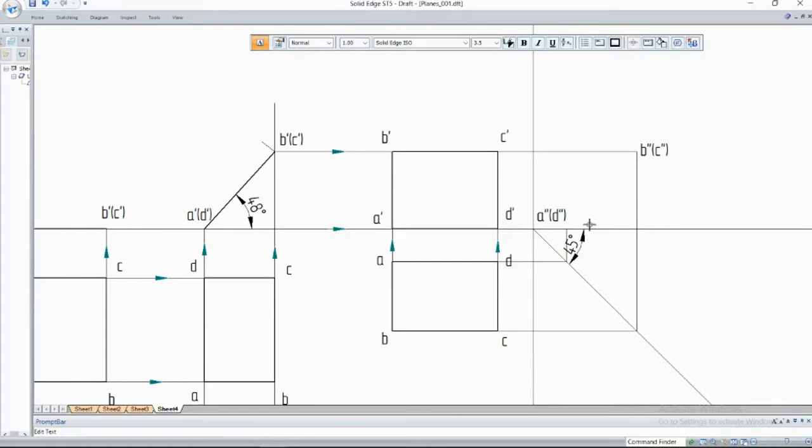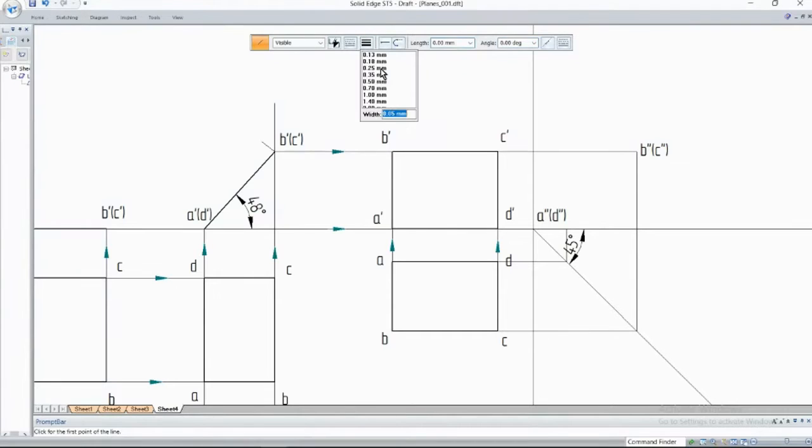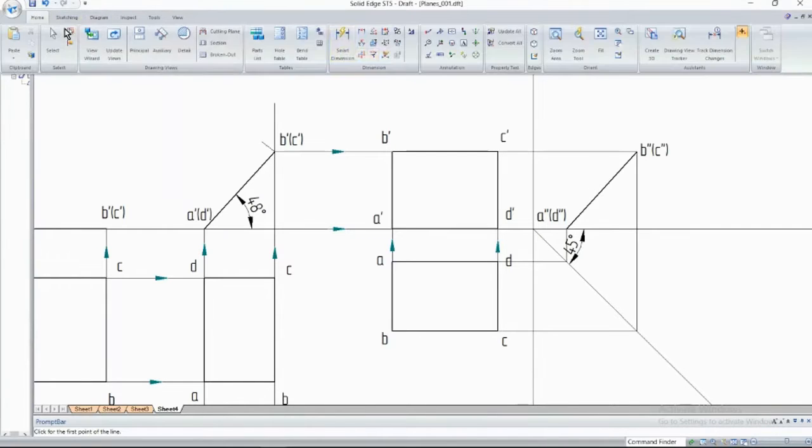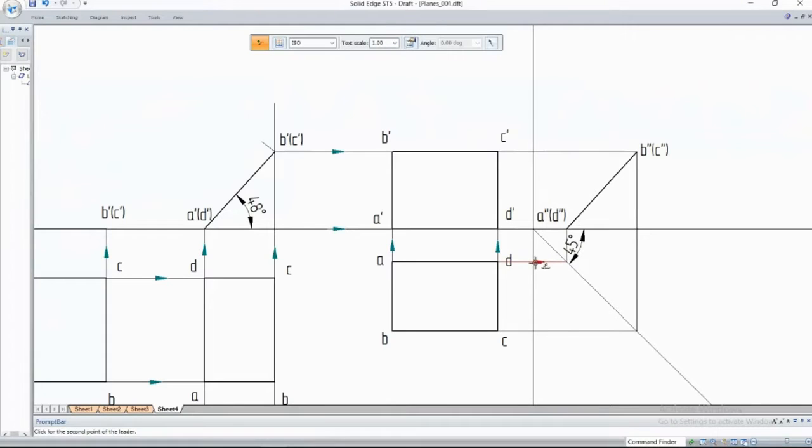After this, you have to join this with thick line. From here to here, join this with thick line. This is how it is visible in the side view, which we saw in Google SketchUp just now. And show the direction of projections. This is to the right. This is the upward direction, and these are to the left here.